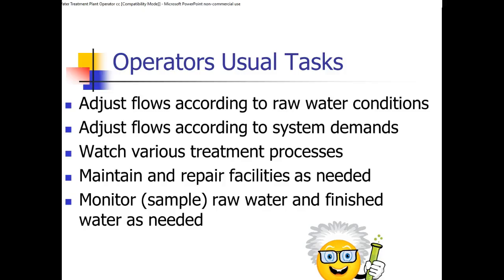So what is an operator's usual tasks? He or she adjusts the flows according to the raw water conditions, adjusts the flows according to the system demands, watches various treatment processes, maintains and repairs the facilities as needed, and monitors or samples the raw water and finished water as needed.